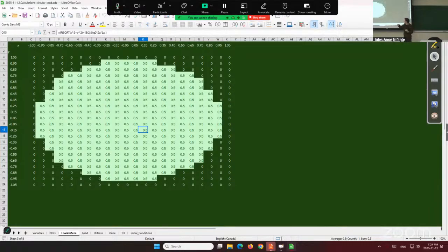In that case, instead of using an equation to generate this, you could take an image file and associate a square to a spot in the image file and then associate coordinates X and Y like I did here, okay, on the plane. So keep in mind that here it was easy for a circle, but you could do that for any kind of shape, for an embankment with sloped sides and things like that. You could use a similar approach to figure out the stress distribution.